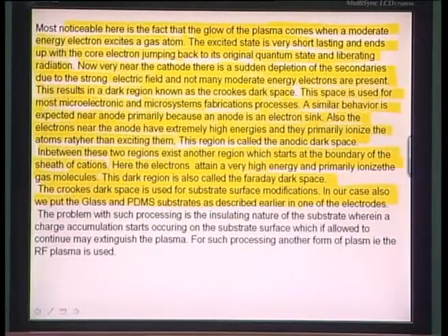So what is one of the immediate problems which come up because we are talking about insulating materials? There is an accumulation of charge on the surface as we put it into the Crookes dark space. There is no way that we are draining off the charge of the surface, rather the charges are getting accumulated within the material, and so after a while if more charge is allowed to accumulate within such a substrate, the plasma may self extinguish because there are not enough electrons to sustain this continuous formation of the sheath, because most of the area of the electrode is covered with such insulating materials, where an electron once gone in is simply absorbed and the substrate gets charged up rather than generating secondary electrons, as is normally the case in metal cathodes present in plasma systems.